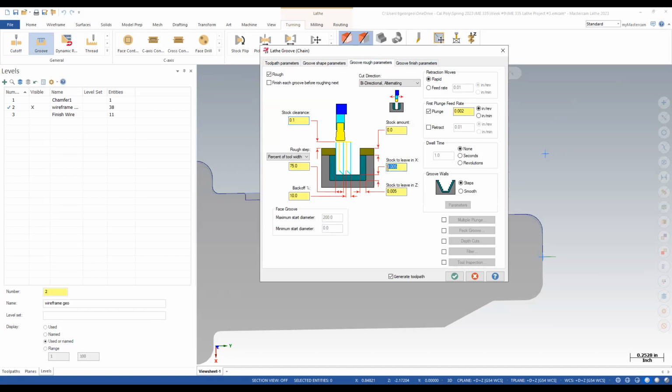And we're going to leave 5 thou for the turning pass. In fact, I would probably only leave like 3 thou just so it cleans up. It barely takes off anything on the next pass. Now, it's going to be really bad if you rough it 75% the width of the cutter. So we're going to do 25%. Sound good? The first one's the full width, but after that, it's 25% of it.